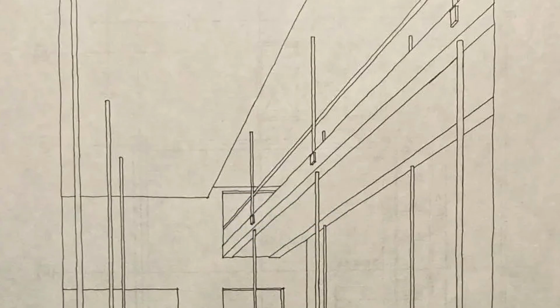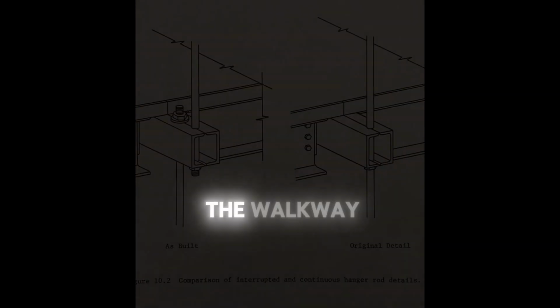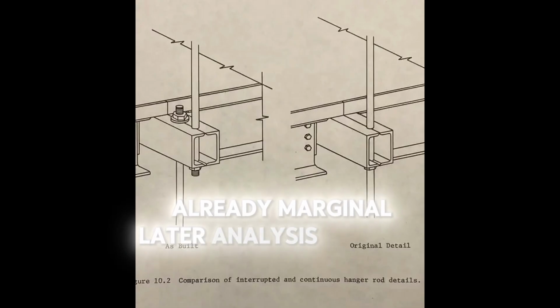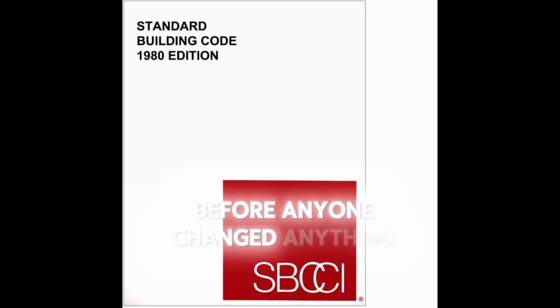Now look at how each walkway grabs its rod, because this is where the whole disaster lives. The walkway is built from two channel beams welded toe-to-toe into a box shape. The rod passes through a hole in that box beam, and a nut and washer under the beam hold it up. So the entire weight of that walkway is bearing on a washer, pressing up against the underside of a welded box beam. That connection was, even in the original design, already marginal. Later analysis found it fell short of the Kansas City building code before anyone changed anything.